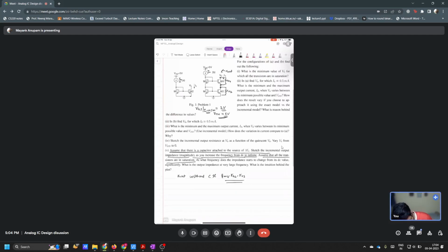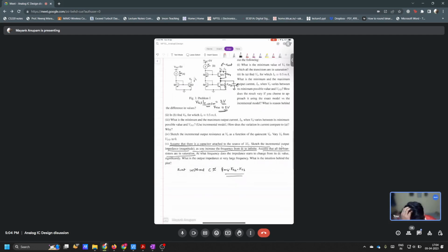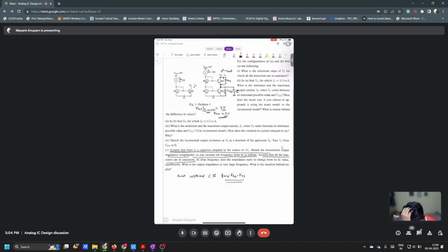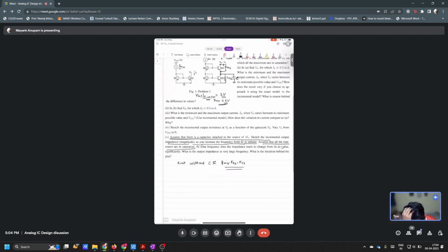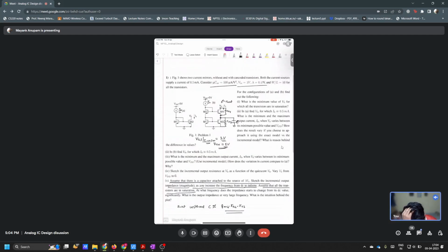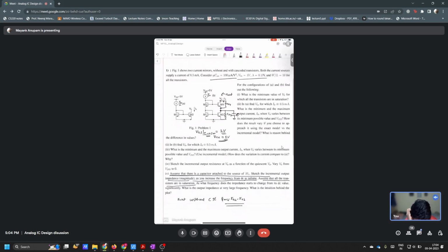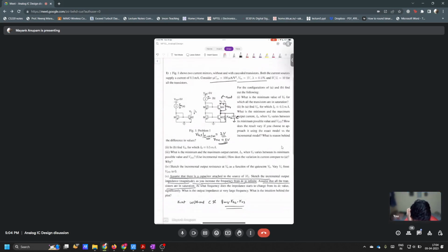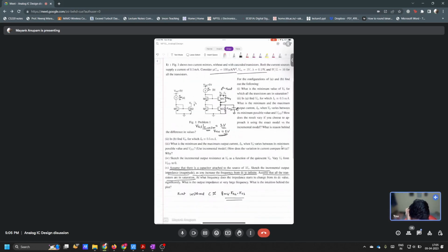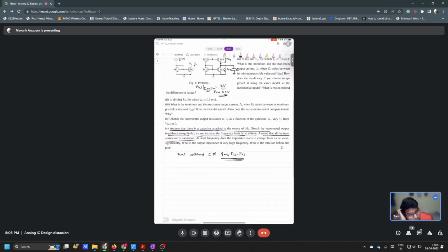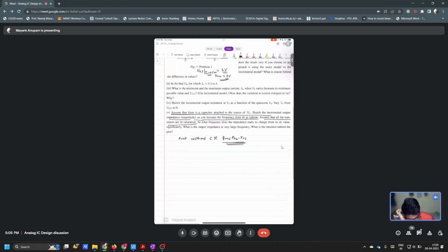So now when you attach a capacitor here, what should happen? It will go parallel with RO2. I'm asking, first tell me what will happen qualitatively, then we'll get into the maths. If we increase the frequency, then the net impedance will decrease, right? RO2 parallel C. So first at DC, the situation is still the same, right? Yes, sir.